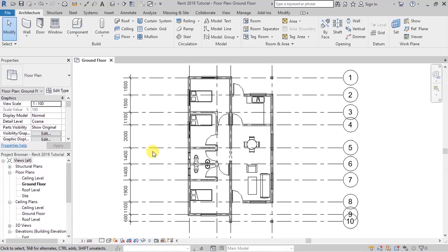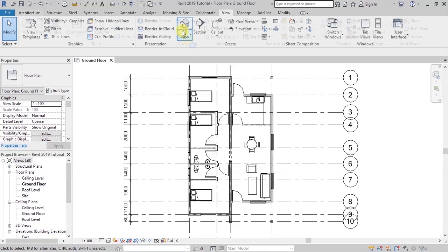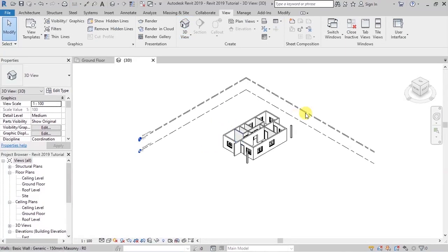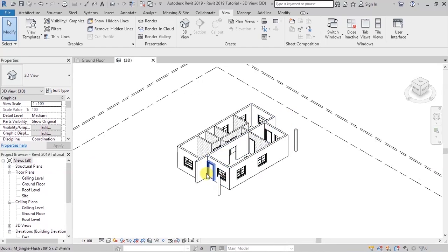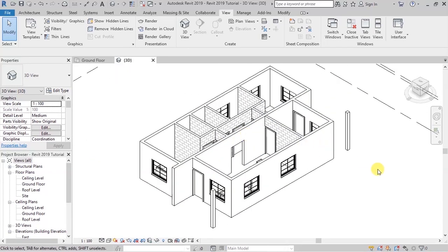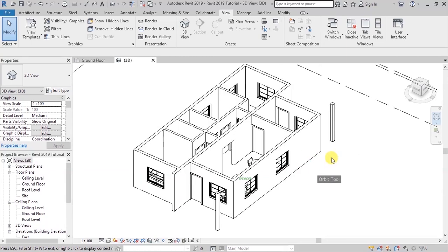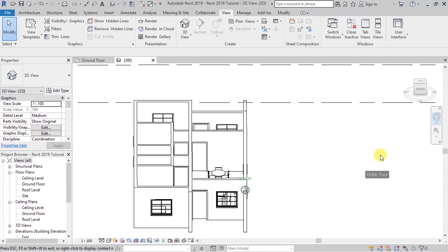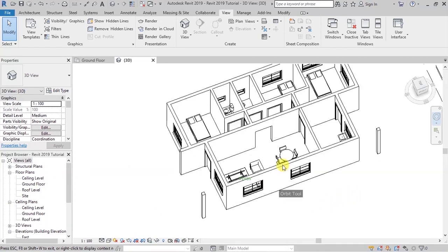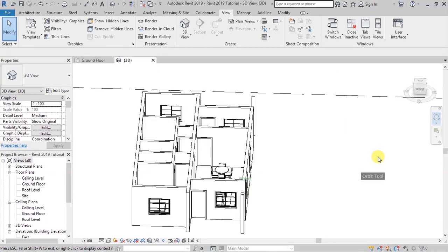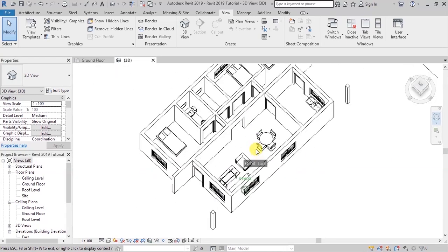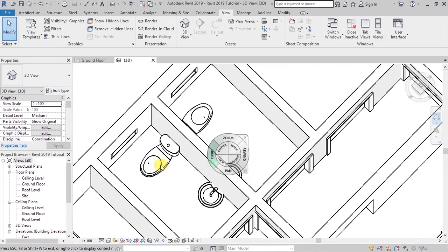We have been consistently modeling everything in 2D, and I've not appreciated how this project now looks in a 3-dimensional view. And I want us to go to view. At the top here, we have the view tab, and then we'll activate the 3D view so that we can see how our project looks like. So when 3D is turned on, this is a look at our project. Maybe I can use this scroll wheel so that it allows me to orbit through the project and see what we've created, what we've modeled in place. So basically that's what we have. The various rooms, the walls, the components, as you can see them from that point.